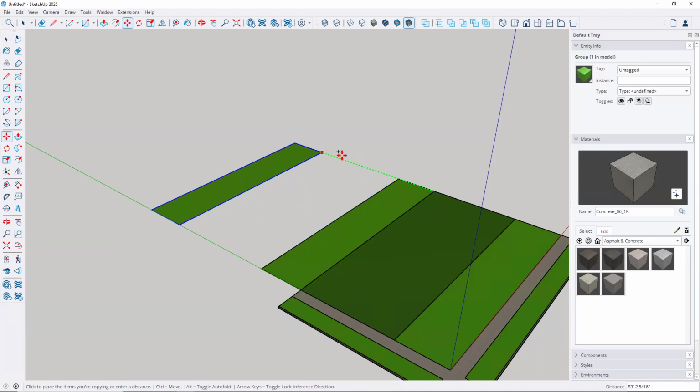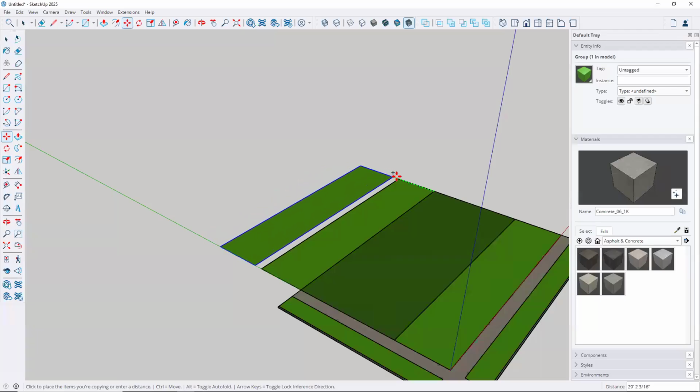All right. Now here's where you have to do things in a specific order. You're going to click on this endpoint. When you click on the endpoint, do not move your mouse. Do nothing other than type. Use the asterisk key. That's the one that is located above the 8, so you probably have to use Shift 8. If you have a number pad on your keyboard, the asterisk is going to be over the 9 on the right-hand side. So asterisk, and you'll see that in my text box there.